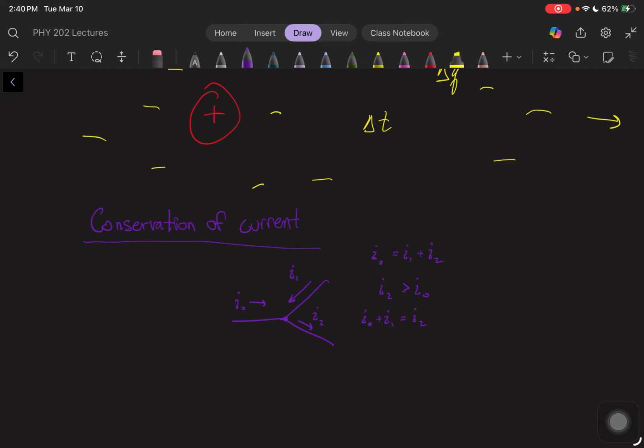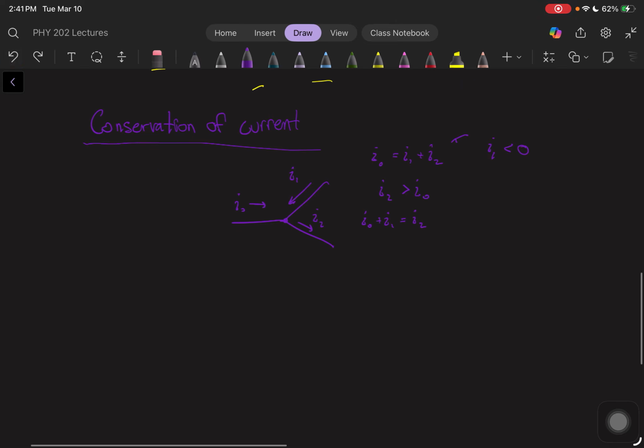And what would essentially happen is if you solve for the currents in this equation, you would get I1 is negative, right? To show that it has to flip directions. And so that's saying that if you started out with it going this way, you would find that you get a negative result, which corresponds to it just flowing the other way. Okay.